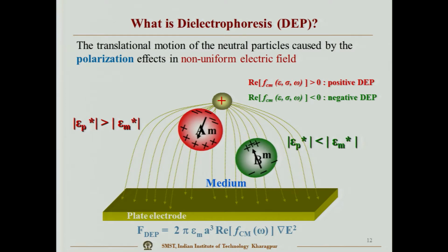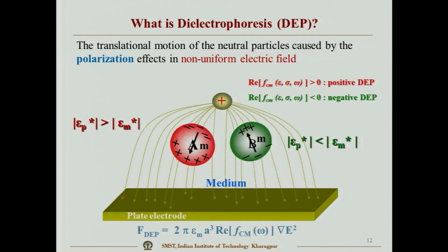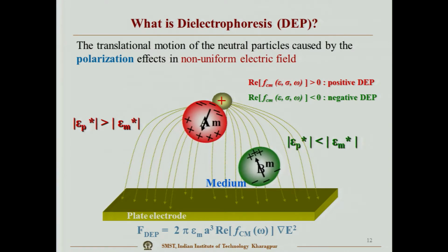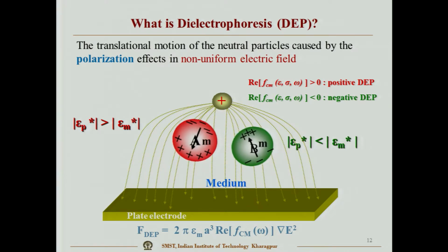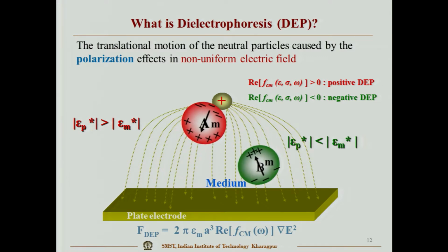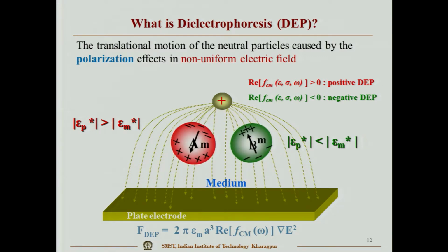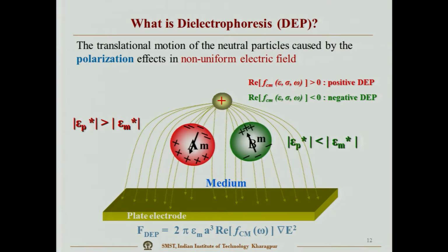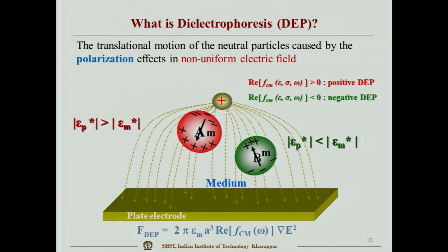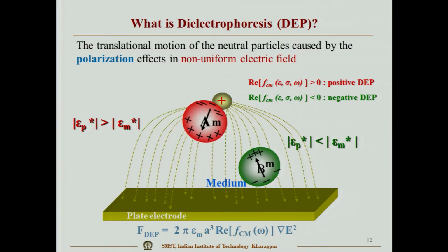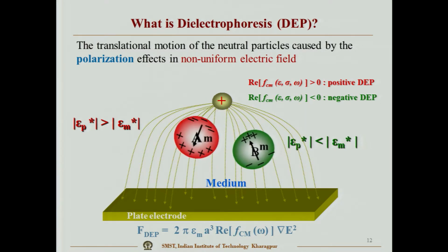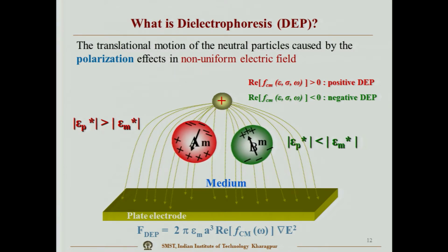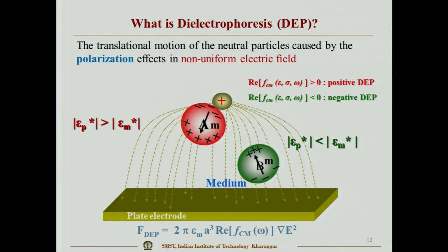So, you require a counter, which can be done with electronic circuits, and after the counter detects how many cells there are, you can go for the bioimpedance properties of the separated cells. From the bioimpedance signal you can do the signal analysis, and you can get the membrane capacitance and the resistivity of the cytoplasm. So, at the cellular level you can build the electrical equivalent circuit.